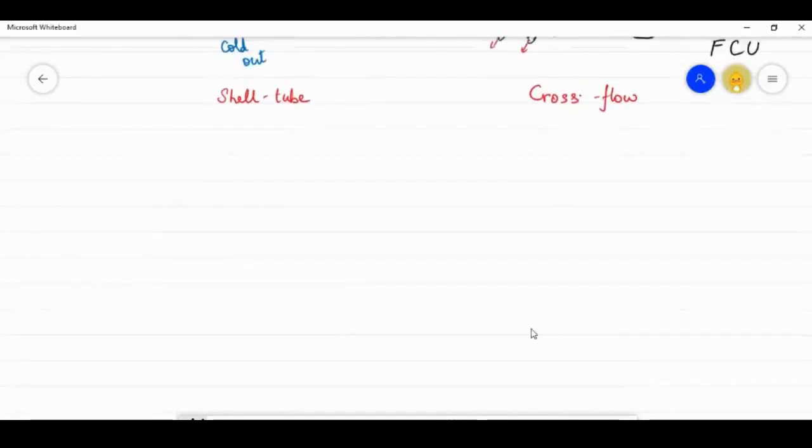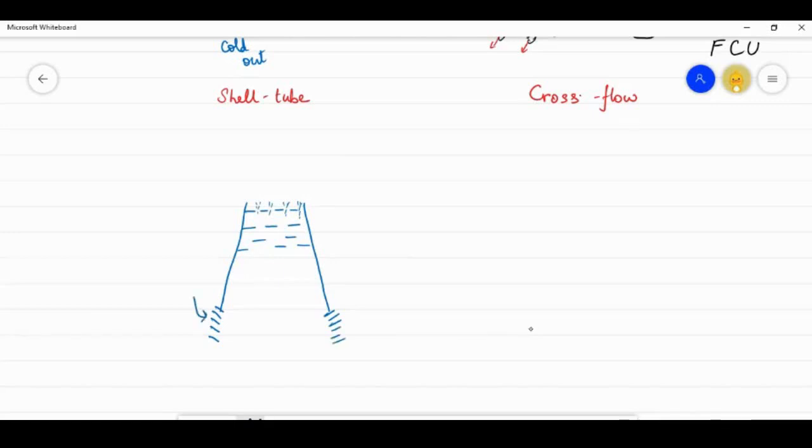There is a third type of heat exchanger called the direct mixing type heat exchanger, as in a cooling tower. Jets of water are sprinkled into the cooling tower, where there are wooden planks present which increase the path of flow of the water. At the bottom of the cooling tower, there are louvers which are like windows which increase the airflow from outside the tower to the inner part of the tower.